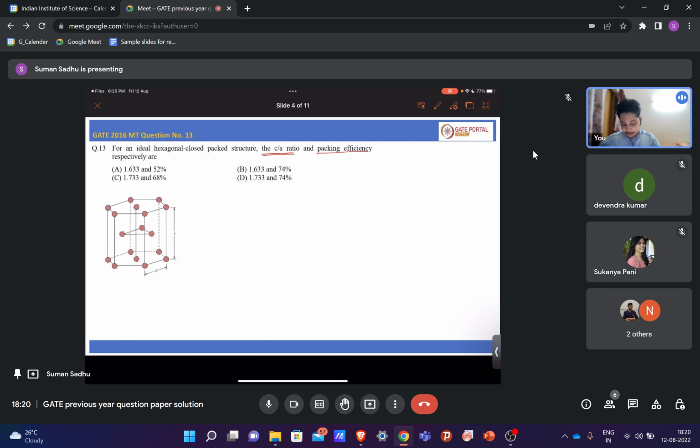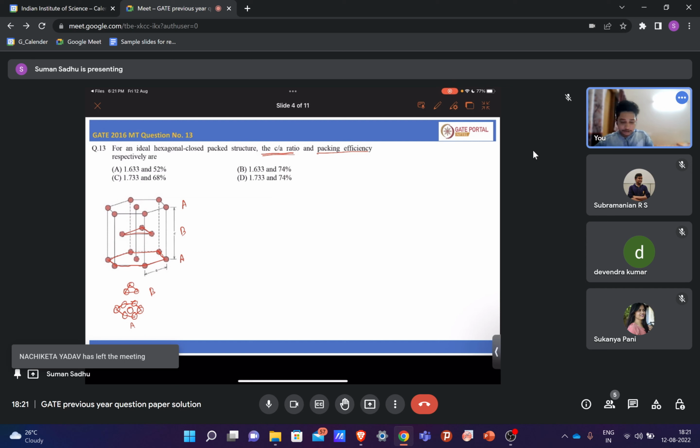So now let us see what the hexagonal close packed structure looks like. It has basically AB type of stacking, so there are different layers of stacking of atoms. This 6 atom set is there at the bottom plane, and this triangular kind of atomic plane, if it is B, so as you can see, this is A type stacking, one atom will be in between of this. So this is A type stacking and this is B type stacking, and again this is A type. So the hexagonal unit cell basically forms by AB type of stacking.